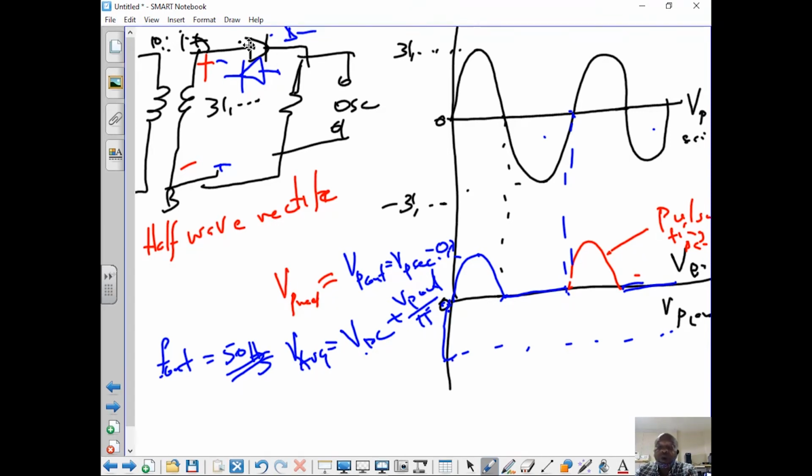Again, sometimes we do not have things that easy. If this is your zero line, and your pulse is something like this, how's your DC now? Negative. Look at it from there to there. It's negative. Now always check this DC. In that first case, the DC from there to there was positive. Now always check whether your DC is positive or negative.